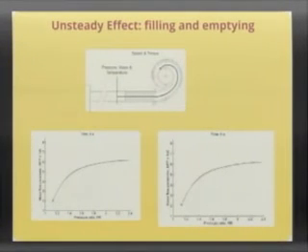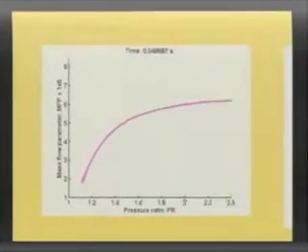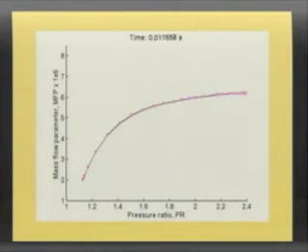There. Now we look at the output. So I posed 2 questions. The questions were, is it quasi-steady? Can I consider a succession of steady states or not? I'm going to plot here what it means to be quasi-steady: mass flow against pressure. If I consider it to be quasi-steady, I ask my collaborators to give me a map of a turbine, its behavior, its characteristics, and I plot it, mass consumed versus pressure. And effectively, this is what I think I would be doing, going up and down that line.